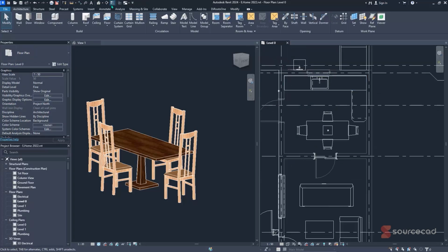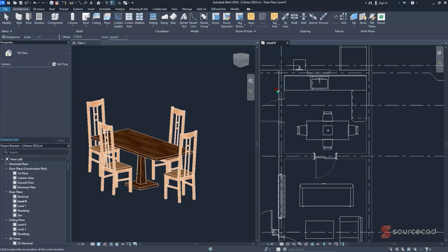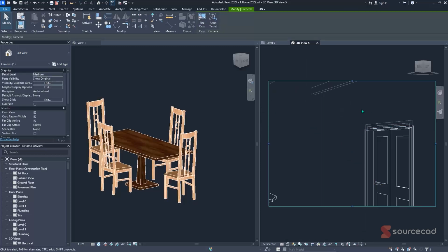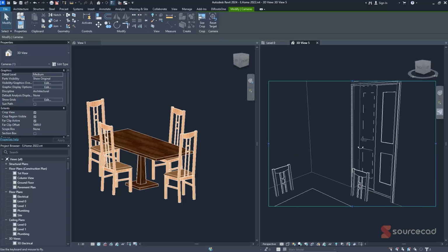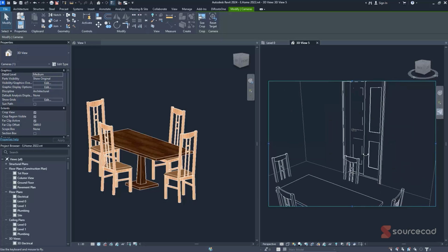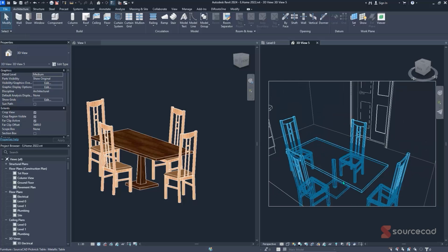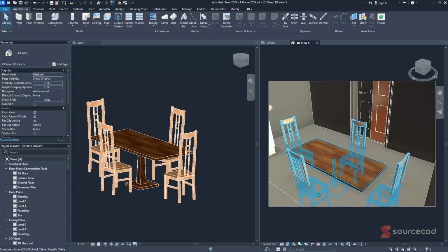And if I was to create a camera, I'll just go to these windows here, drop down, and create a camera from this point to that point. Then I'll simply use the fly command just to look down. Currently it has been placed at this level. It's actually sinking into the ground. So let's use realistic colors so that we can see how things look. And then I'll simply change the level at which it has been placed.